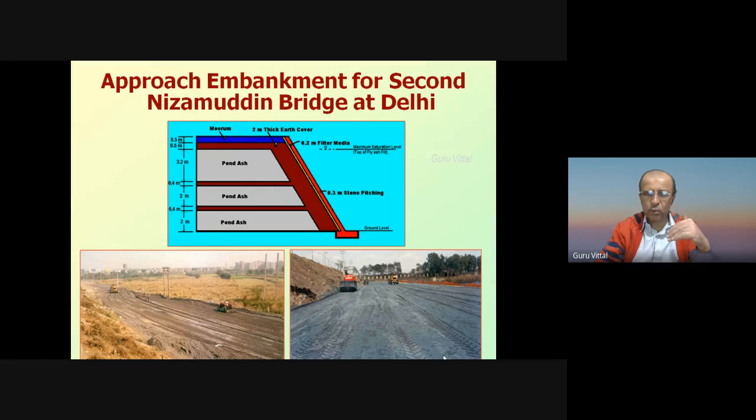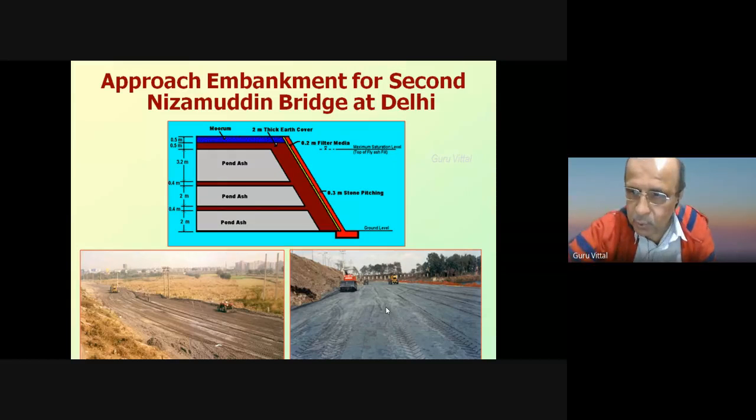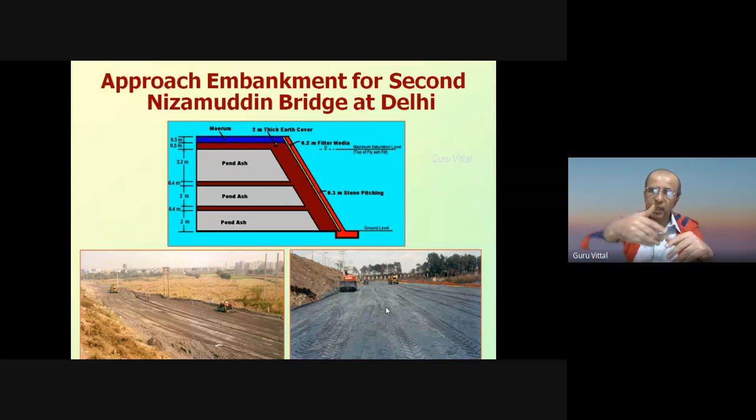So in this water pond, we had to construct our embankment. In a waterlogged area, how do we construct our embankment? There are 2 ways. One is that we drain out that water, we remove the slush, and then we construct our embankment. The other is that if the ponded area is very large, and if you cannot drain out that water, we take gravelly type material. We back dump our gravelly type material, and after it comes up above the level of water, we construct our normal embankment.